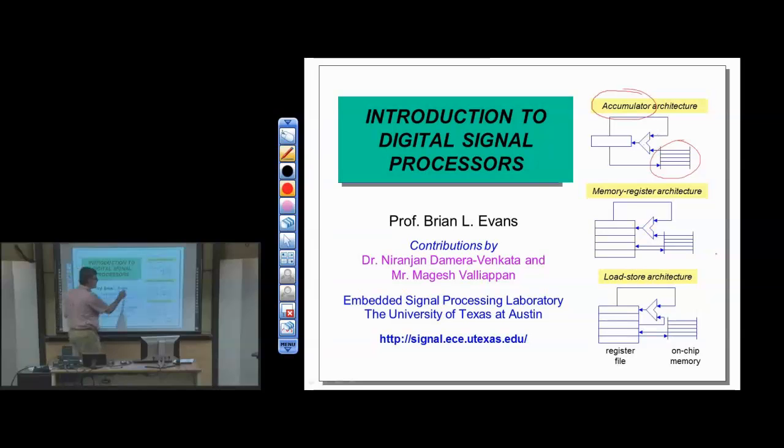The adder tree is, if I add, let's say, 32-bit numbers together in this case, I get a 33-bit result, worst case. If I add two more 32-bit numbers together, again, I get 33 bits, worst case. Now I add those up, and I get 34. Okay, so I add two numbers together. We did this in the Mandrill demo, or if you're watching the video, we will do it in the Mandrill demo in Lecture 5, Part 4. Okay, so two 32-bit numbers give me 33. Four 32-bit numbers, I need 34 bits. So when do I need 35 bits?